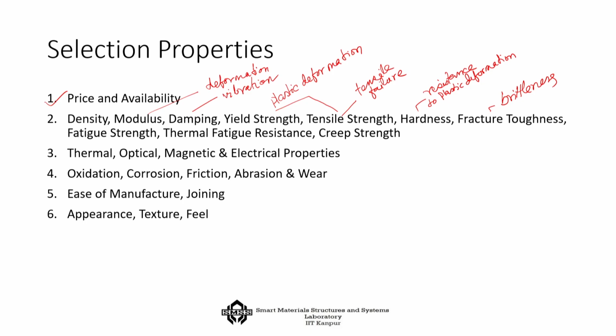Then there comes fatigue. Day in and day out, if you subject a system to repetitive load, then there is a kind of weakness, the cracks develop in the system, and as a result sometimes you may get a sudden failure out of it. Many of you might have tried this simple thing, that if you take apparently ductile copper wire and you repeatedly twist it, or deform it, bend it, up and down and up and down.